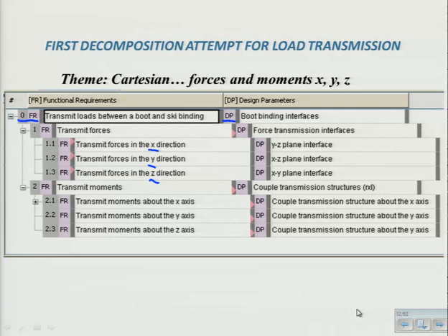So what does that look like? Some plane oriented in YZ. So similarly for the other three. So there's Fx, Fy, Fz. So we think, well, I get 6 degrees of freedom. What am I missing? The moments. So I'll transmit forces and transmit moments. That way I've transmitted all the loads.